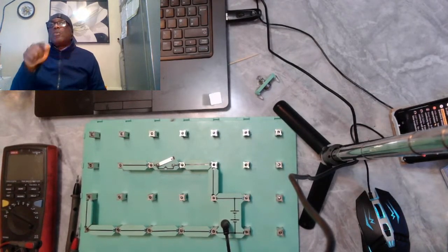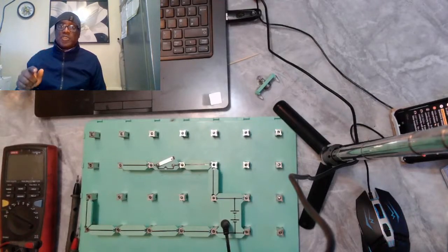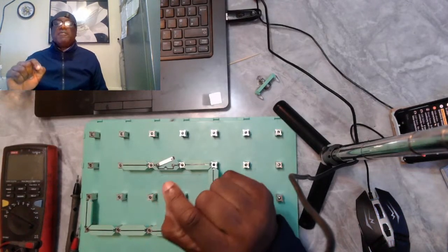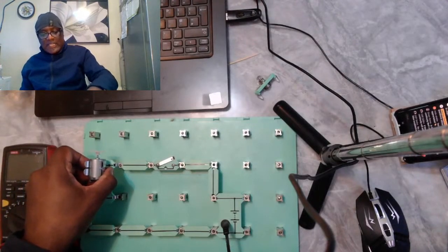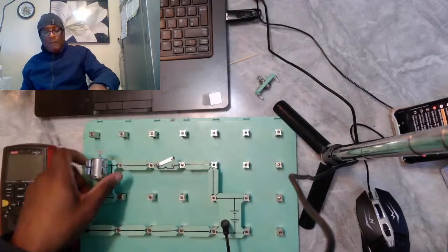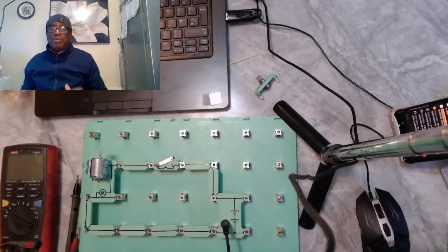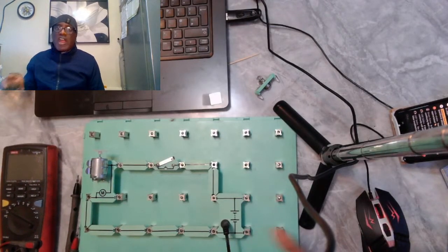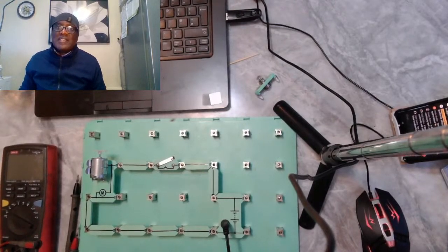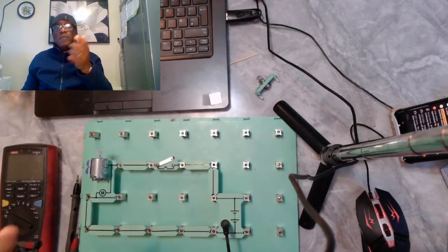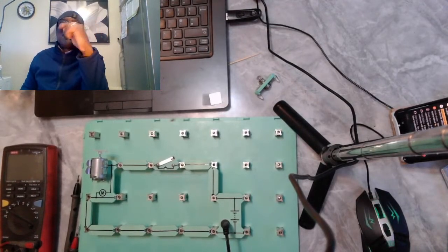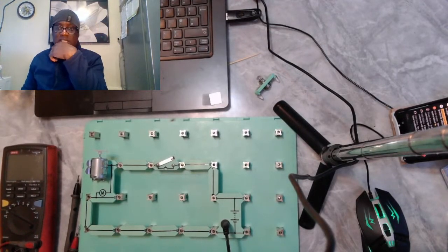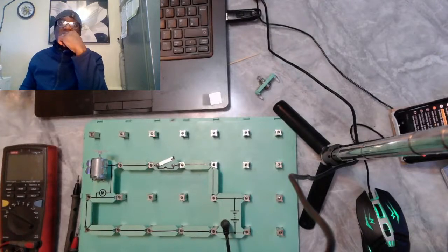But if you go down the lane of voltage drop, you can catch everything that is in that circuit, because now you are putting the circuit under pressure by running current through it. You have got voltage running current through that circuit, and it will manifest itself if there are any issues there.